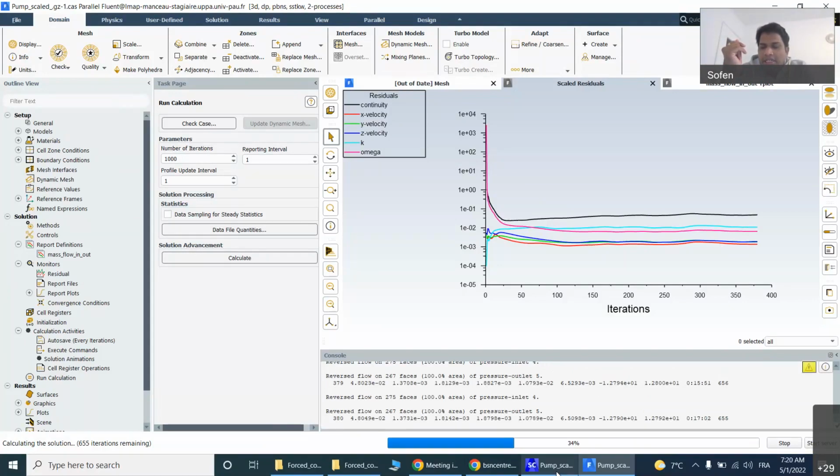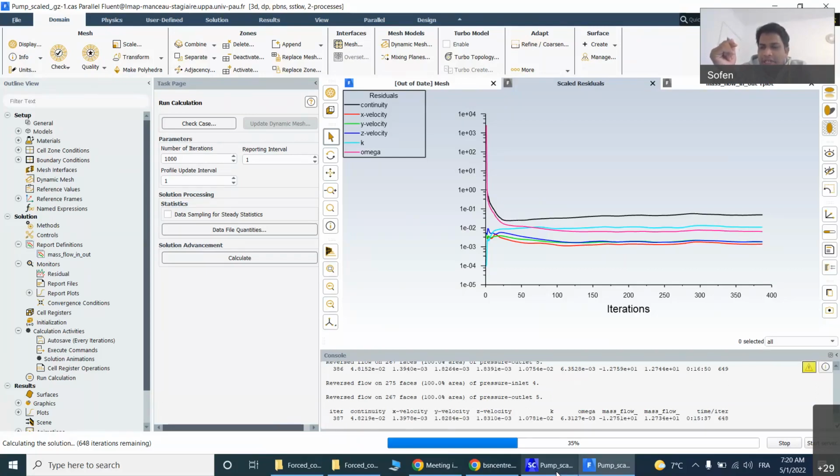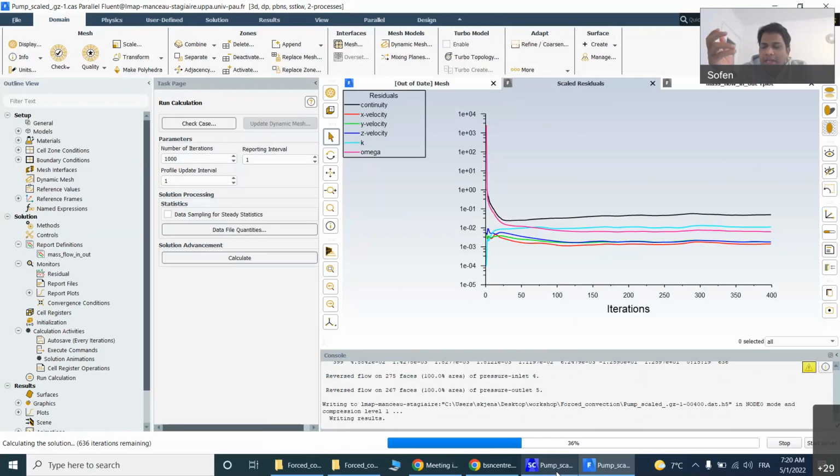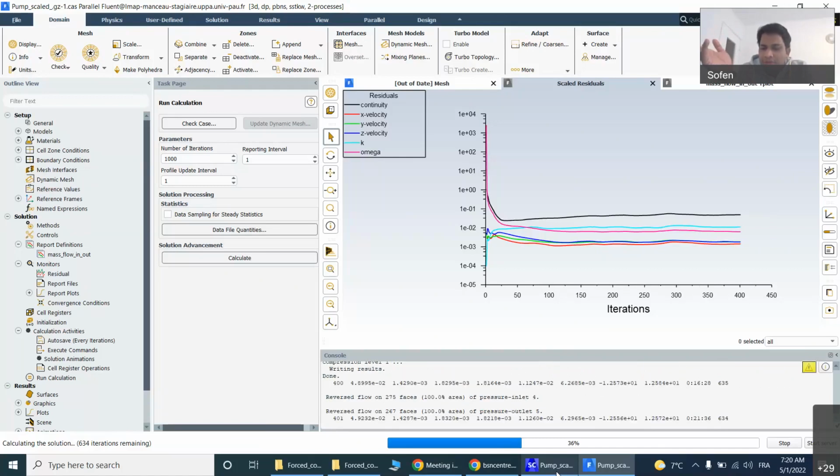In thermodynamics, you have an equation of state for density, maybe a kinetic theory model or the ideal gas model, P equals rho RT, where density is a strong function of pressure. But in normal or isothermal conditions, your density is not a strong function of pressure. So that's why you can call it an incompressible flow.